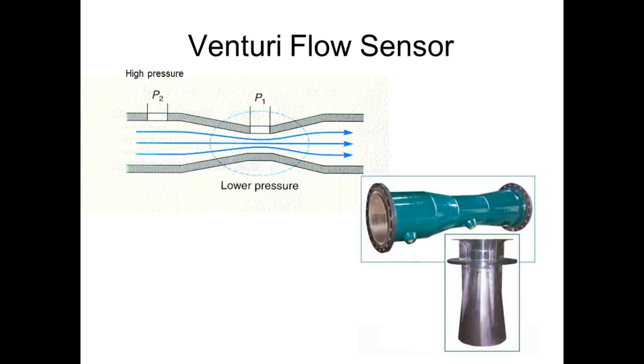By the way, this is what we use on both of our manufacturing lines to generate a vacuum. It's just that we don't have this port 2, we have port 1. So what happens is when this air comes flying through there, it creates low pressure and causes the pressure to go down, right? You understand? So over there on our manufacturing line, we don't have any vacuum pumps. What we do is we use the flow of the air that we got, we send it to a Venturi like this, and then that pressure generates.